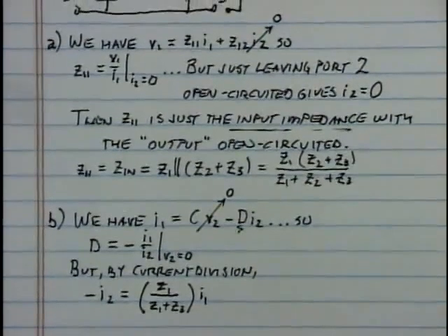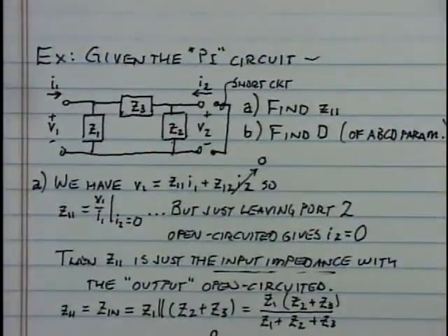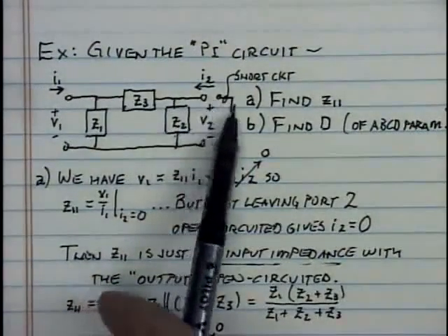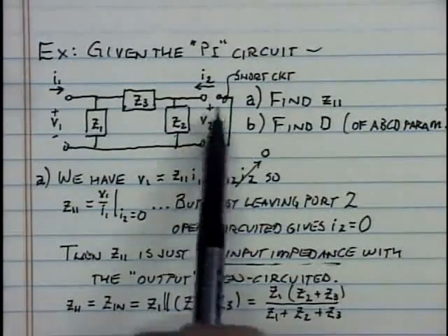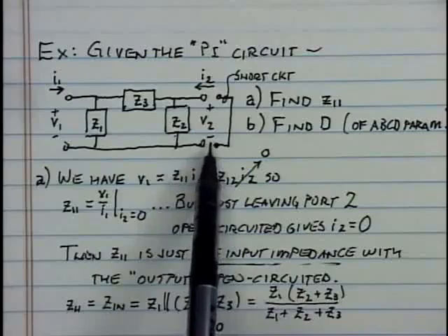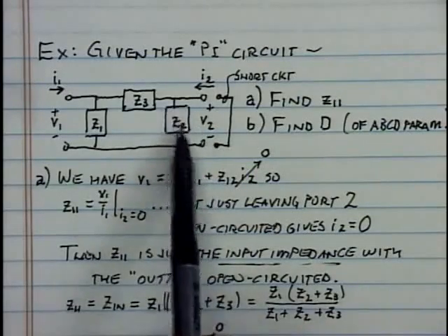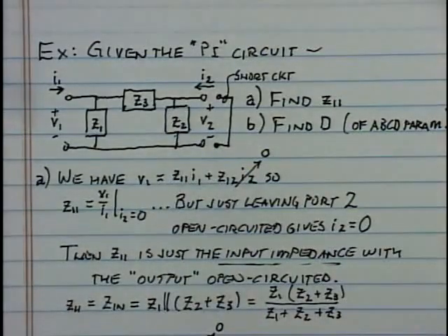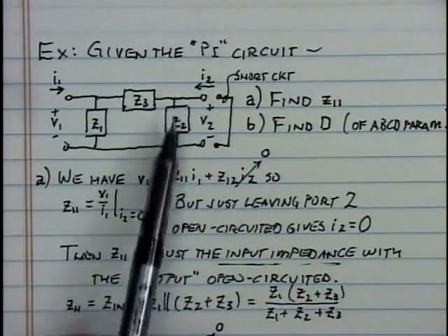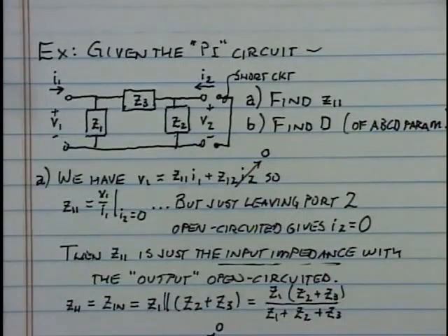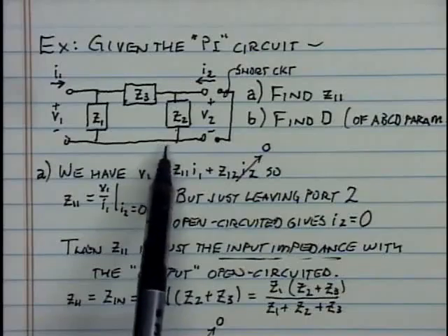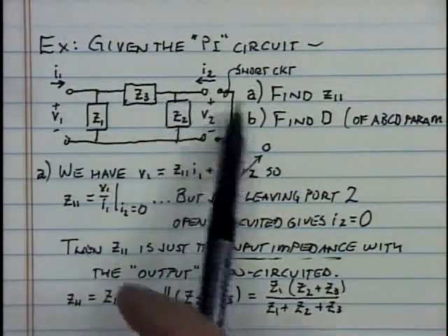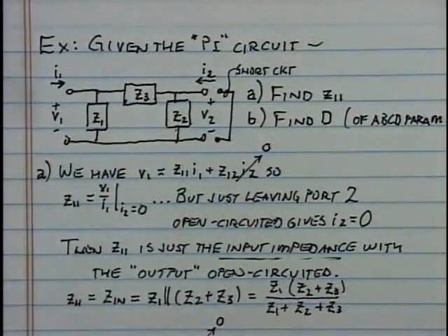Let's look at that original circuit, imagining that that short circuit is in place. Okay, now first of all, if the short circuit is in place, we no longer have to even include Z2 in the circuit at all. Z2, that impedance Z2 is short-circuited. Any current flowing on this wire or on that wire is going to flow through the short circuit. It's not going to flow through the impedance Z2.